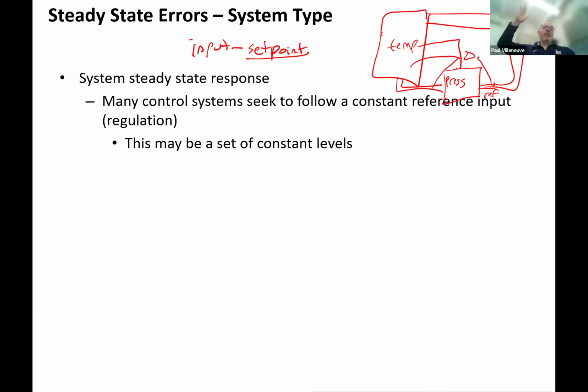And so one of the things that was amazing to me, we actually got to go inside the containment building and look at this sight glass, and the operators had to periodically, I think it was once every 2 hours, walk by and measure what the level was on the sight glass. So sight glass is based on basic physics principles, right? If you don't have a blockage, the level in the tank is what's indicated on the sight glass or the sight gauge. So that's always bulletproof.